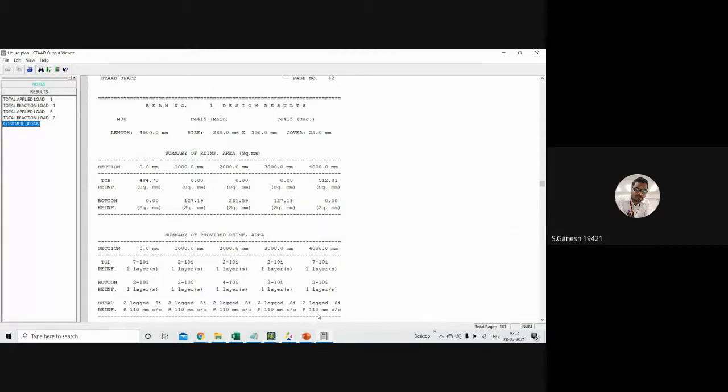There you might have studied singly reinforced, doubly reinforced, but when you come and see in the software, it will not show you singly reinforced or doubly reinforced. It will show only a basic result: AST, the moment, the spacing. Our role is to check that AST is sufficient and the shear force travelling through that beam is within the safe limit or not. If shear is failing, then you get more cracks and you need to take care of your stirrup spacings. These are the major roles of a structural designer.